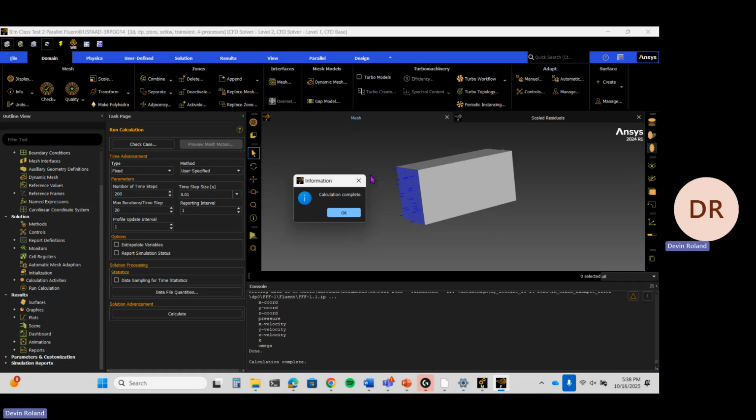And let's say your time step is such that your fluid particle moves from here to here in that one time step dt, then that's okay, because you're only going from one cell to the next. But what if your time step was bigger and so you move over here? The simulation basically skipped this whole block if your time step is too large.